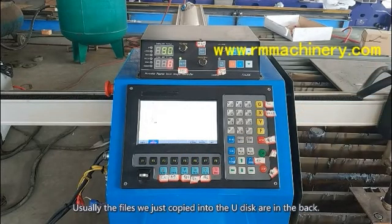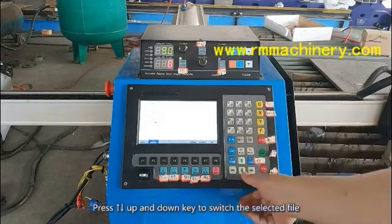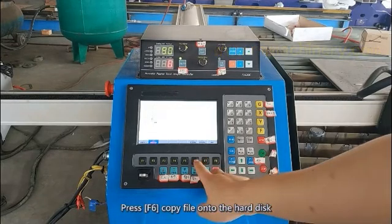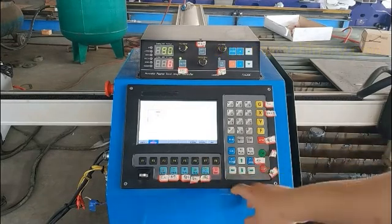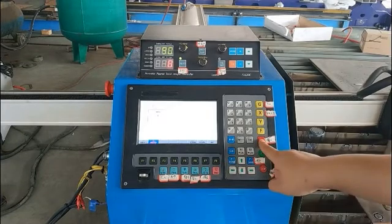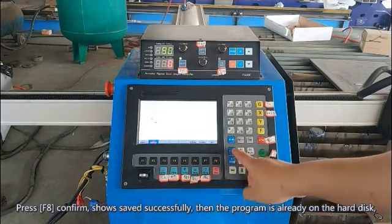Usually the files we just copied into the U-disk are in the back. Press S to flip the page. Press the up and down keys to switch the selected file. Press F6 to copy the file onto the hard disk. Press F8 to confirm. It shows save successfully, then the program is already on the hard disk.